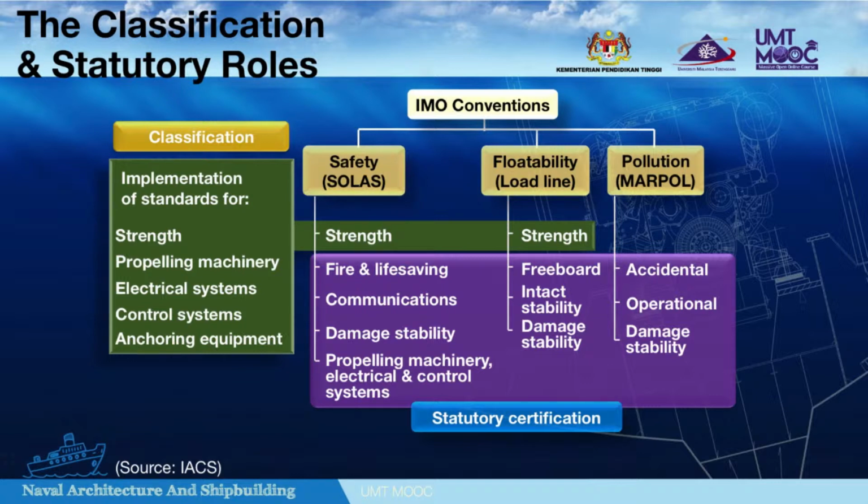In 1930, the first International Convention on Load Lines was adopted and was based on the principle of reserve buoyancy, although it was recognized that the freeboard should also ensure adequate stability and avoid excessive stress on the ship hull as a result of overloading. It has long been recognized that limitation on the draft to which a ship may be loaded makes a significant contribution to her safety.